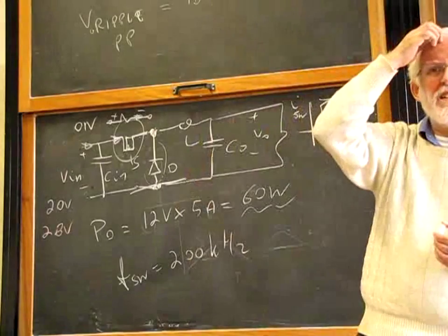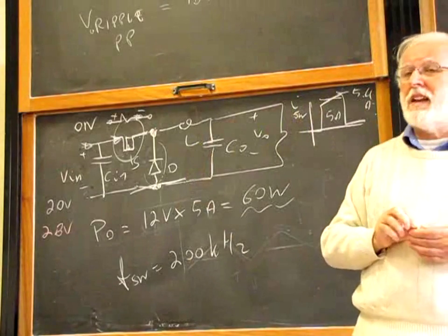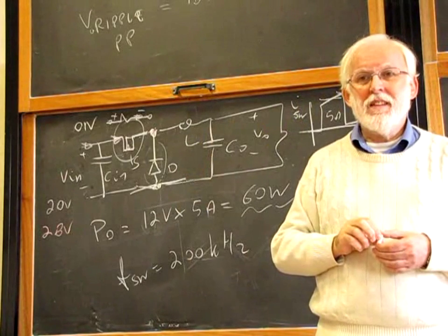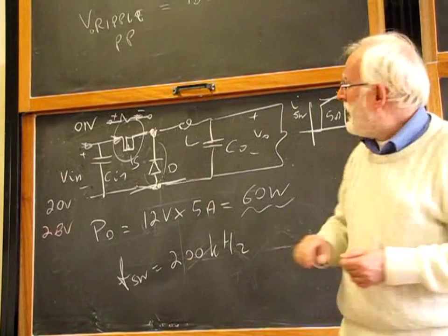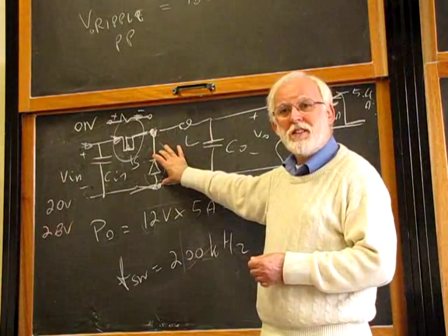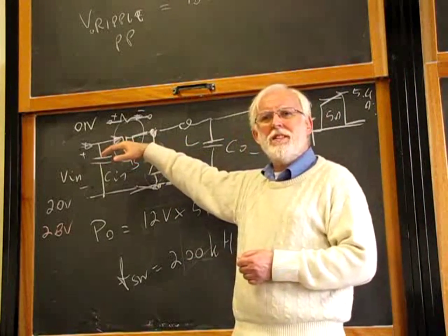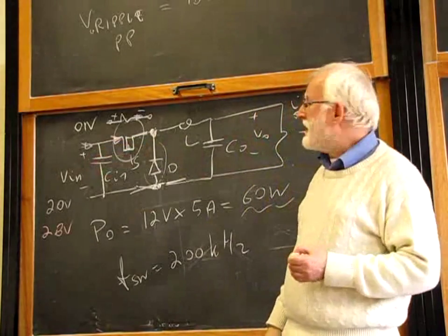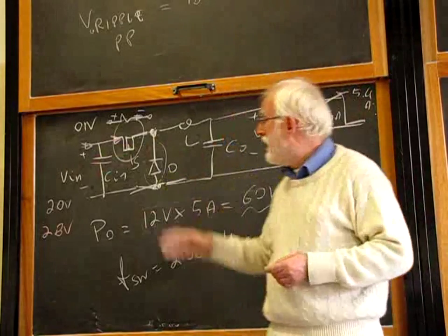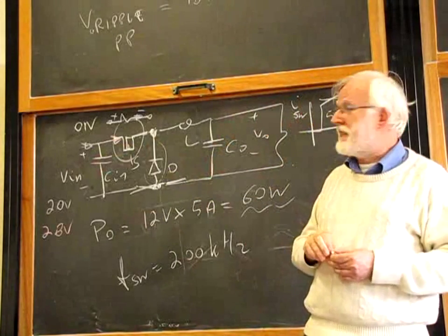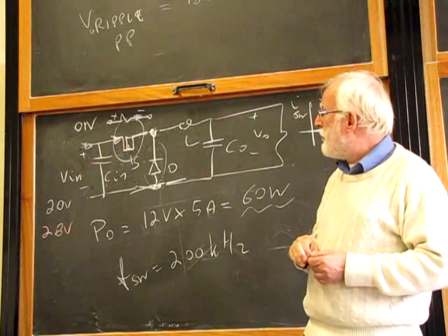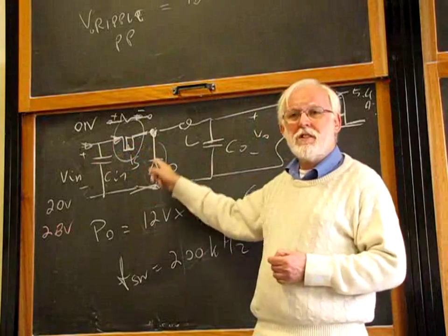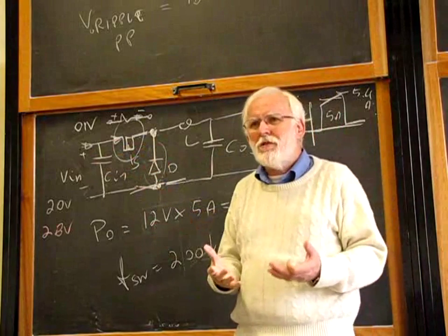Say again? One order of magnitude lower of what? With respect to the voltage drop across the diode. Oh, one order of magnitude lower than the voltage drop across the diode. So you say, I won't have to worry about this voltage drop. Well, it could be okay, but the situations in which buck converters can work are quite different. Having a voltage drop here that is quite lower than this voltage drop is okay. It means I have at least one good switch.